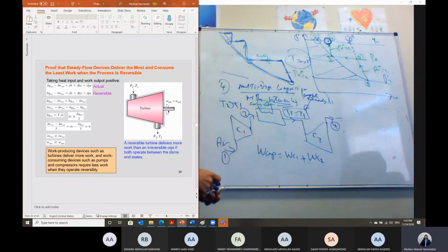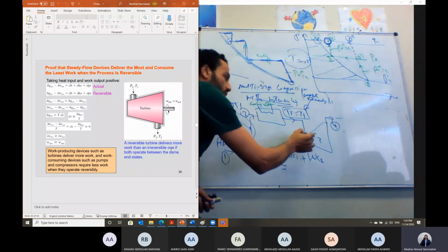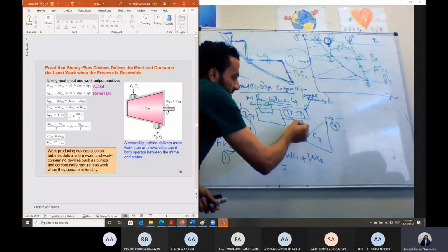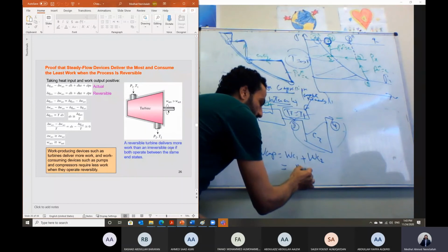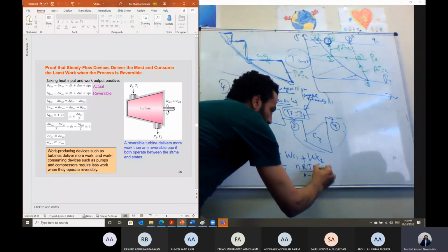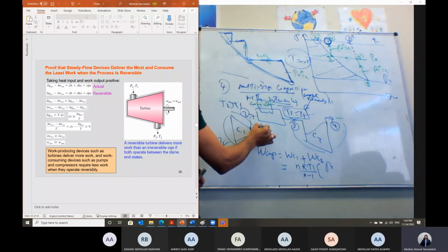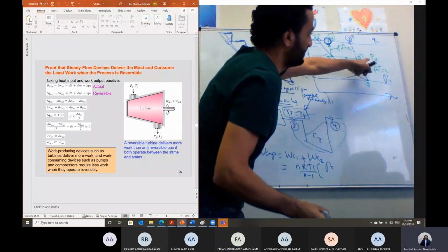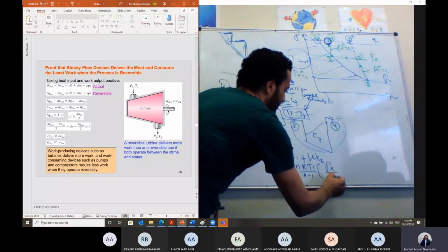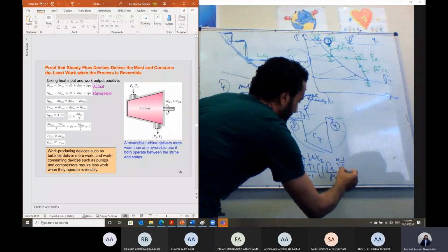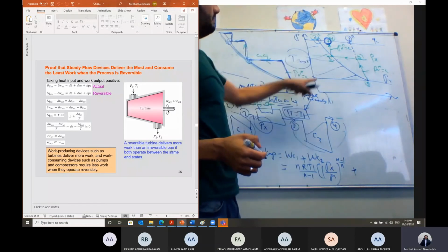Okay? In this case, the compressor work will equal, this is a polytropic from 1 to 2, and this is state number 3, 3 to 4 is also polytropic. So polytropic, we have proved the relation. It will be nRT1 divided by n minus 1 multiplied by P2. P2 in this case will equal to what, Shabab? We call it the intermediate pressure, Px. So it will be (Px over P1) to the power (n minus 1) over n, plus the work of the second compressor. We said T3 is the same as T1 for complete intercooling.